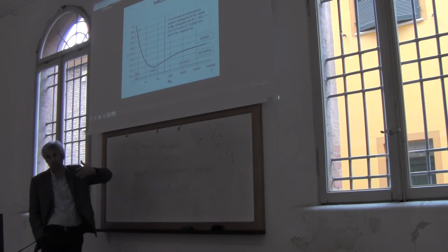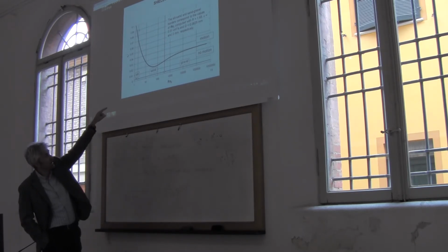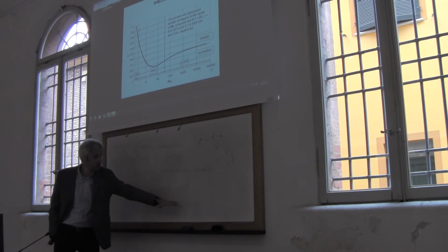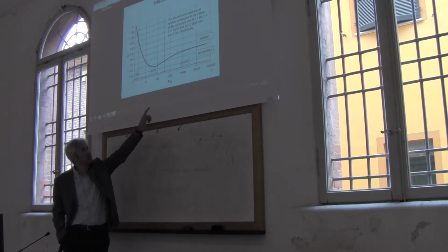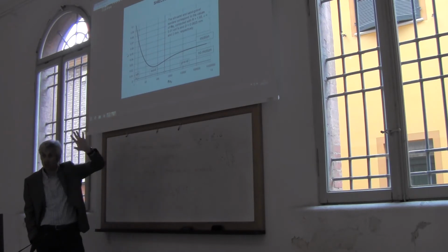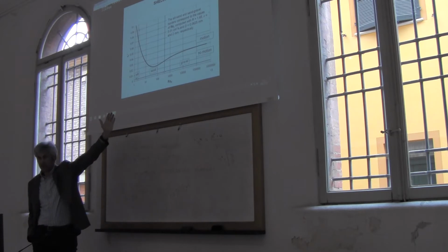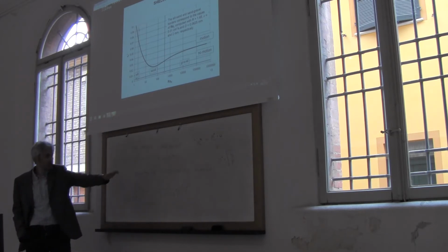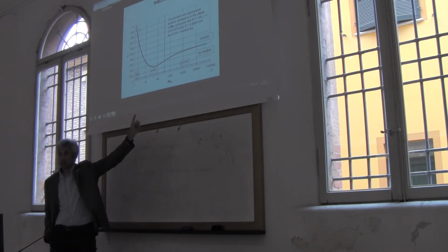He probably did a dimensional analysis, and then he proved it in the lab and depicted here the dependence between the Shields parameter and the Reynolds star. And here you don't see the star, the symbol is different, but this is Reynolds star. What he found was that for high values of the Reynolds number, indeed the Shields parameter is constant.